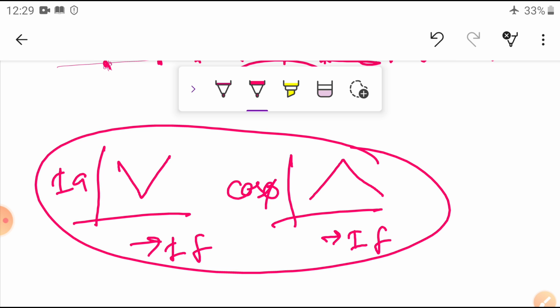You know that due to the change in excitation to the DC rotor, we change the back EMF, resultant voltage, power factor and armature current. Once the armature current changes, the torque also changes. So what are the different torques? Already we know the pull-in torque, the nominal pull-in torque, the pull-out torque, and the reluctance torque, which we have already seen.